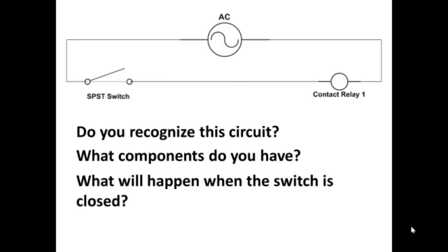power the relay. Now I show the relay going off as the current reverses, but remember that this is 60 cycles per second, which means that 120 times a second the voltage goes to zero and then keeps on going right over to the opposite polarity. So the relay doesn't have time to de-energize, even though I show it de-energizing in the diagram.